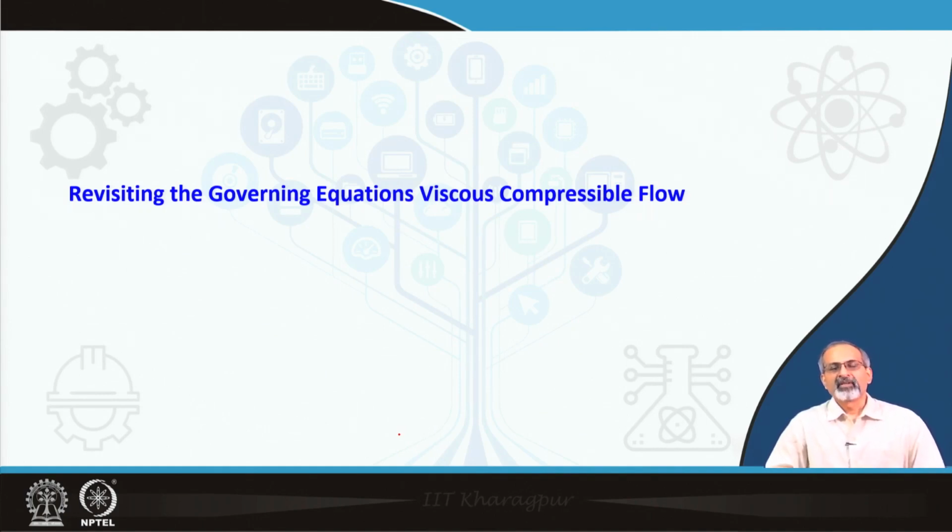Again, if we confine ourselves to only inviscid methods, then certain very important phenomena like separation of the boundary layer, shock wave boundary layer interaction, etc., go unaddressed, and therefore, finally, there is no way but to look at the complete viscous compressible flow equations.